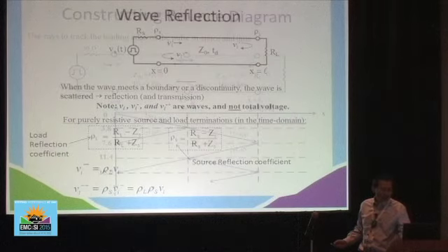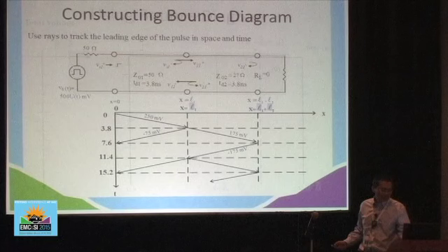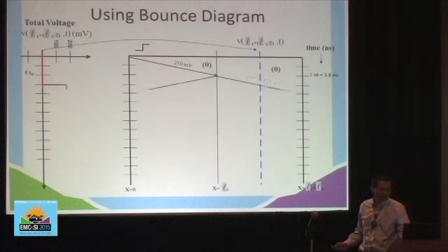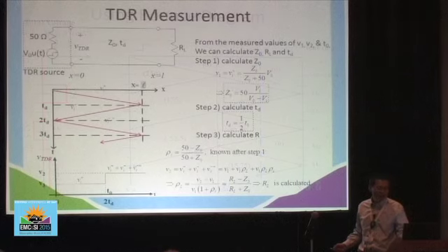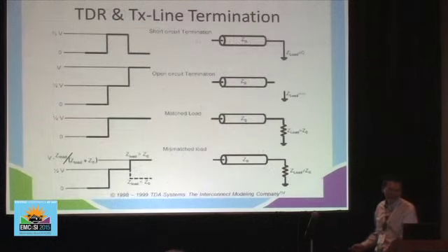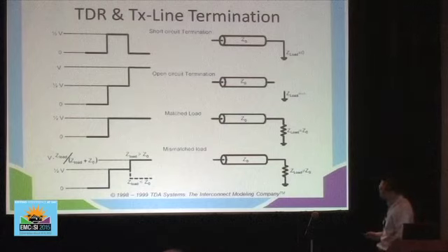All right, so TDR is a really important measurement. Not only does it measure the characteristic impedance, it also measures resistive terminations, as we'll see later on. Here, let's do a few simple cases in the previous diagram.